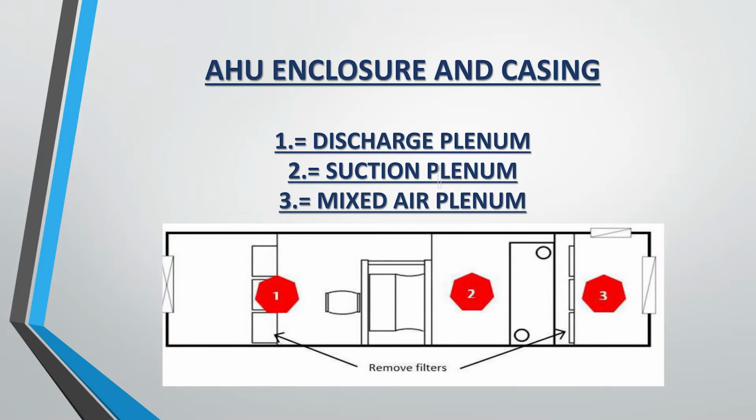looking at this air handling unit enclosure casing, if you look at this part here, this is the dividing wall. This is like a plug fan. So on this side we have positive pressure, on this side we have suction pressure. We've got filter, coil. This says remove filters. You can or you can't, it's really irrelevant. If we're going to test this section, we're going to test it in a negative, just like Troy said. This section should be tested in a positive.